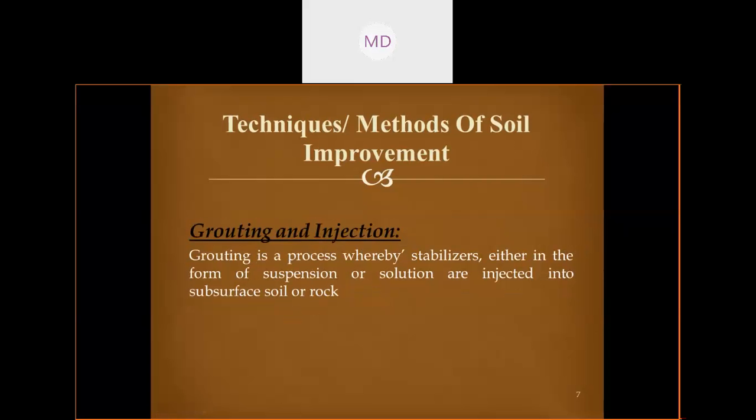And this grouting has various applications. It generally controls the groundwater during construction. So one more process of controlling the groundwater is grouting. Then it fills the voids to reduce excessive settlement.